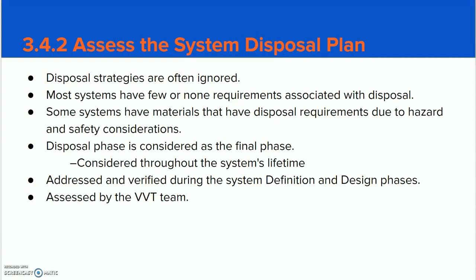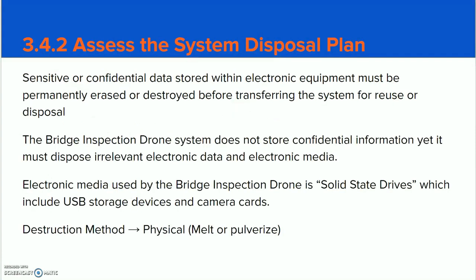Disposal phase is considered as the final phase, addressed and verified during the system definition and design phases, and assessed by the VVT team. It is important that sensitive or confidential data stored within the electronic equipment must be permanently erased or destroyed before transferring the system for reuse or disposal. The bridge inspection drone system does not store confidential information, yet it must dispose of irrelevant electronic data and electronic media. Electronic media used by the bridge inspection drone is solid-state drives, which include USB storage devices and camera cards. Destruction methods are physical, either by melting or pulverization.